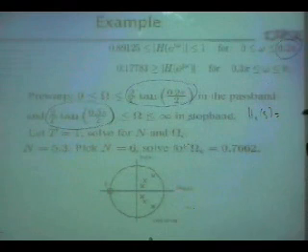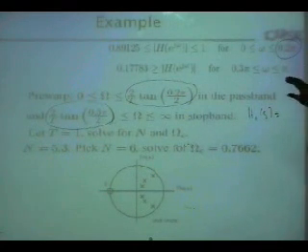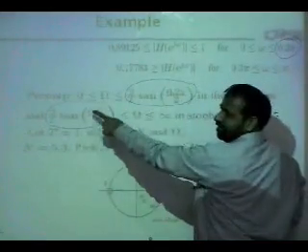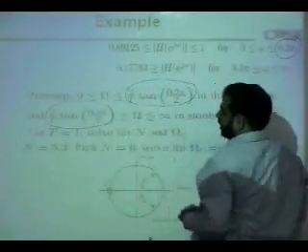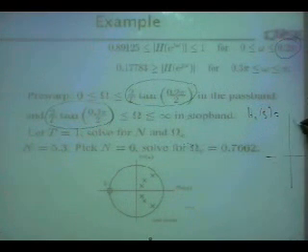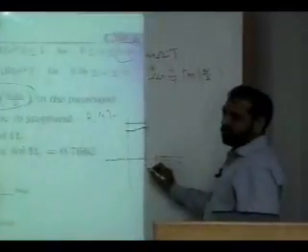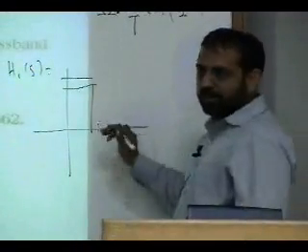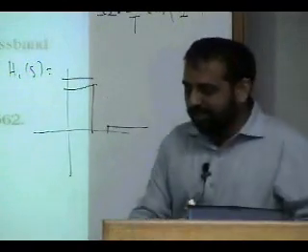First, once you are converting specs from discrete domain to analog domain, you need to use the same transformation. Okay. Now you start your design. Okay. Design you start exactly the same. You say, okay, this is my specs, but only now this will no more be 0.2 pi. This will be some other value. This will no more be 0.3 pi. This will be some other value. But other than that, everything is the same.